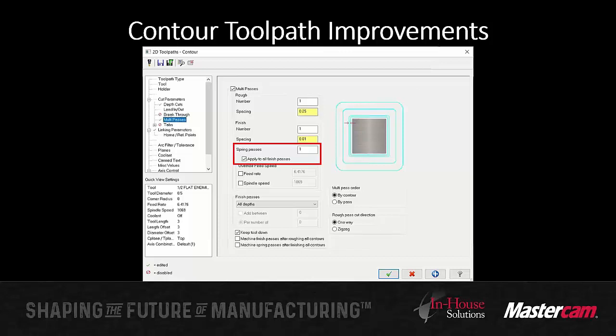But as machinists, what we often know is if we're dealing with small tools, let's say we're cutting a profile with a 1/8 end mill, and just because of the depth I need to go, it's hanging out pretty far, I'm going to have some deflection issues. And so the path that I'm creating, because my tool is deflecting or bending, if you will, I end up with a tapered pocket. So by having a spring pass, cutting one more time around, or two more, however many times I want, cutting theoretically nothing, it's just removing the rest of that material for me. So rather than applying that only to the very bottom, I can now apply that to all finish passes, whether it be all depths, or just in between, for every third depth or whatever I have selected under my finish path parameters on the bottom there, right below that.